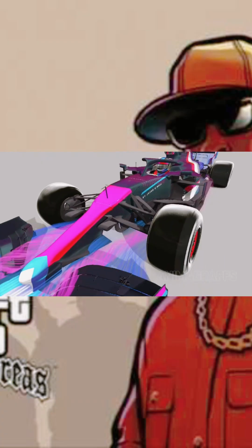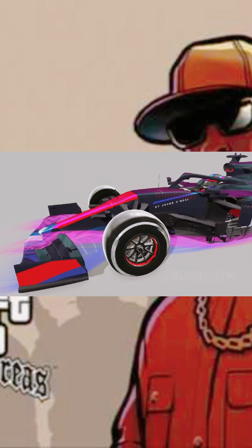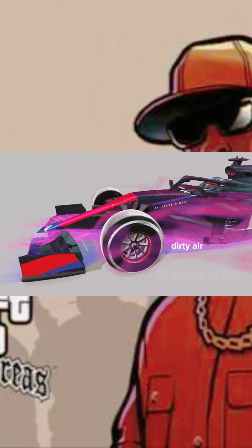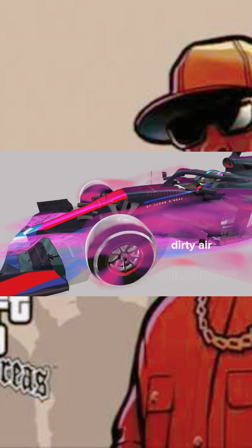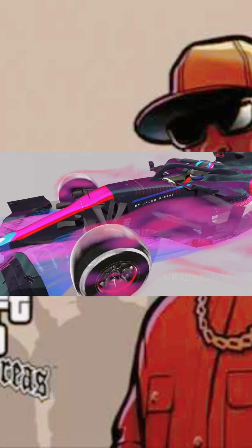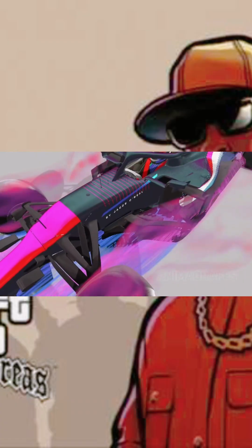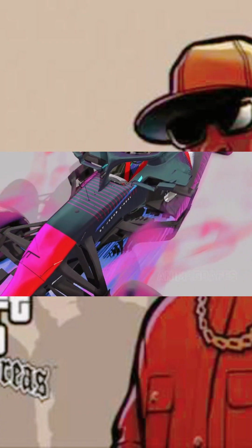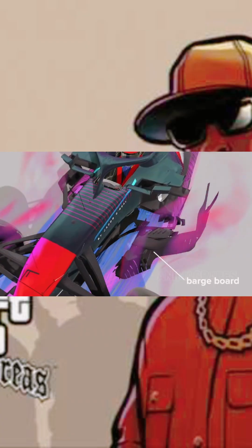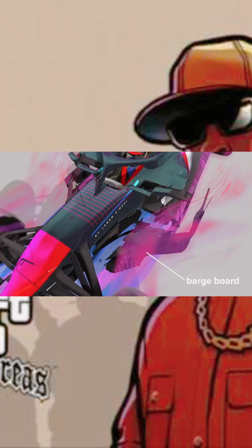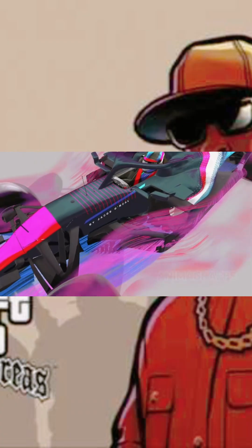As a matter of tradition, F1 cars don't have fenders, and the open, spinning wheel and tire combination is a major source of dirty, turbulent air. Turbulent air is unpredictable and not very useful for aerodynamic goals, like generating downforce. Directly behind the tires, the barge boards condition or clean up some of this airflow while also pushing lots of dirty air away from the body.